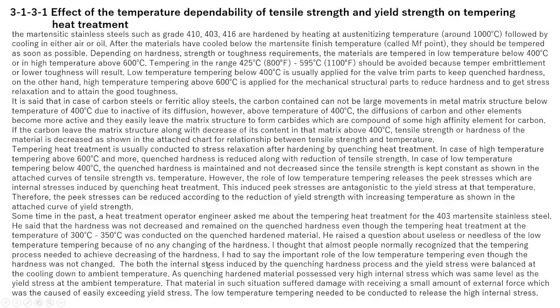I thought that almost everybody normally recognized that the tempering process is needed to decrease the hardness. I have to say the important role of low temperature tempering even though the hardness is not changed. Both the internal stress induced by the quenching process and the yield strength were balanced at cooling down to ambient temperature.